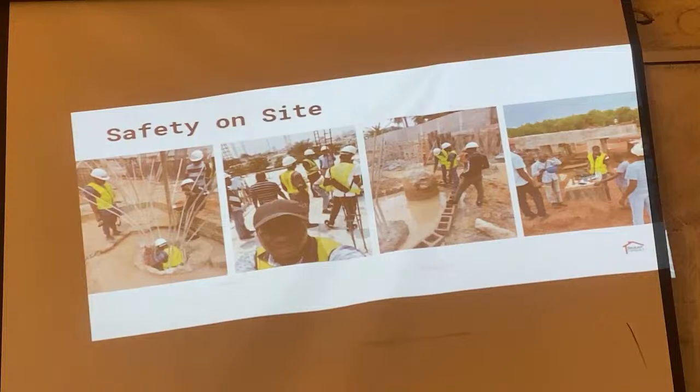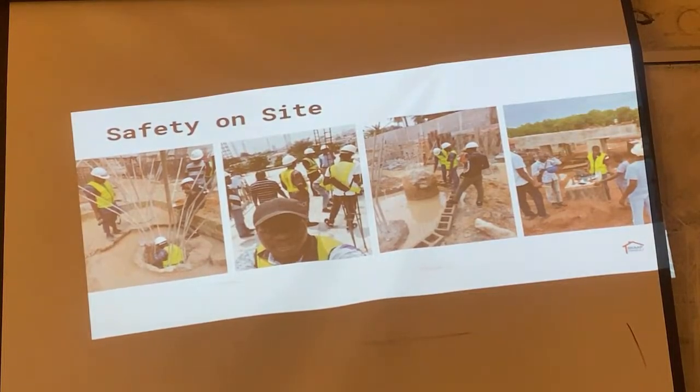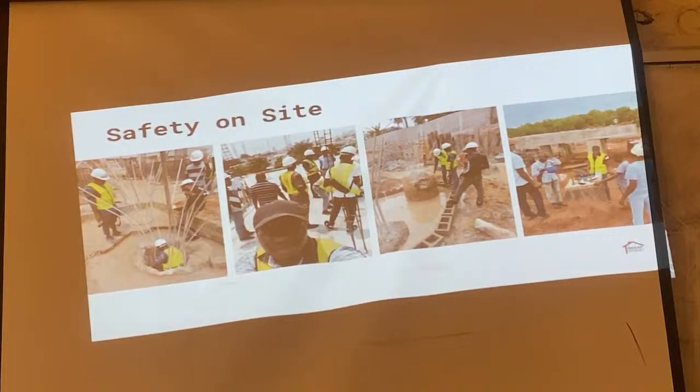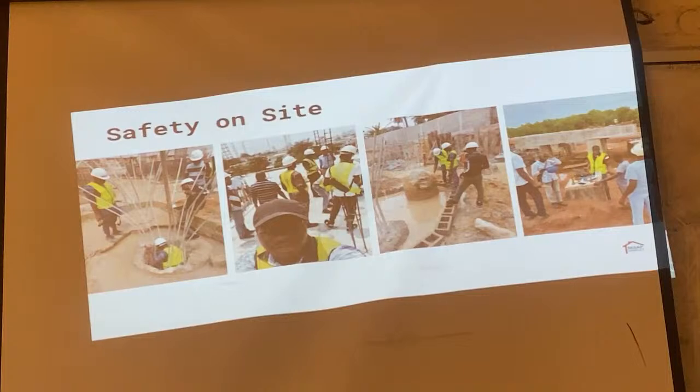Yes. So when you are doing a pile load test, you are trying to stress that pile enough to see how much load it can take, right? But can that actually test for homogeneity of that concrete? Exactly. It can't.